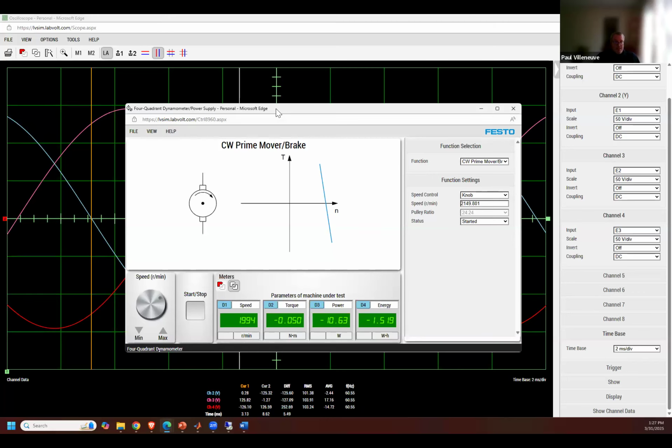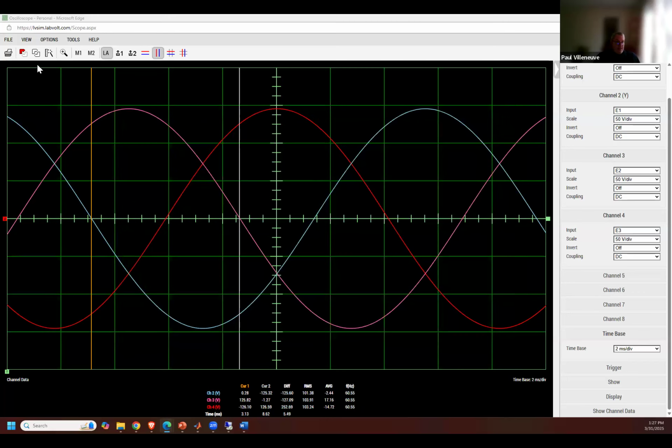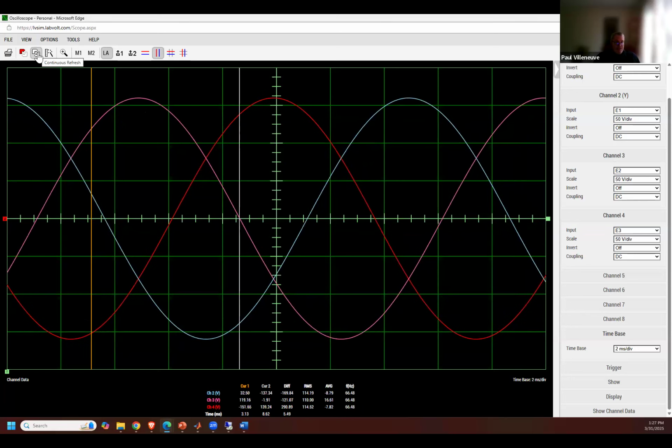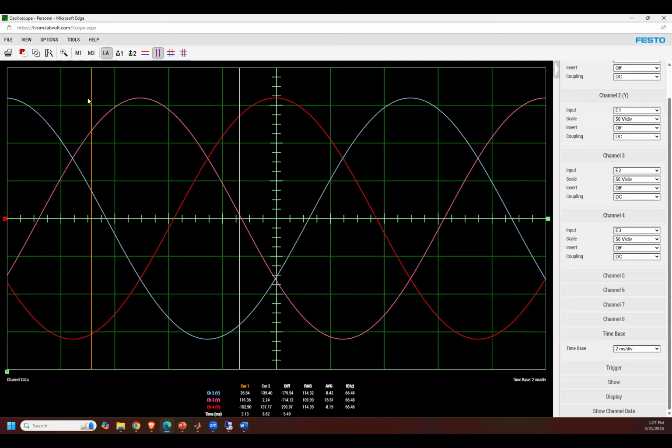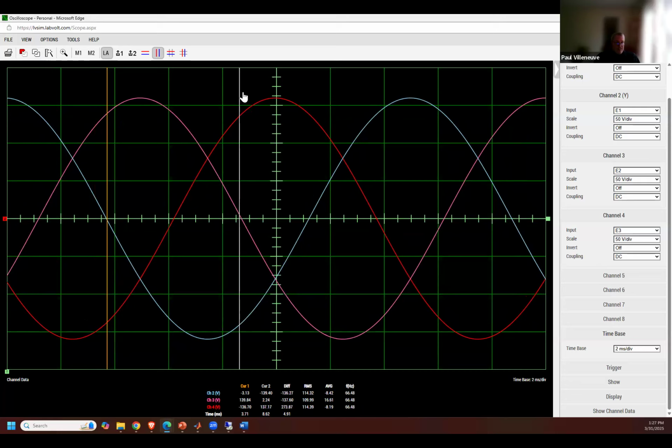1994, close enough, right? Now I'm going to make this so that I can get different data. And you can see it's much tighter, right? So I'm going to pause it here to here. And if I take the difference here, I can get it. But this one's a little bit harder because before when I said 1800 RPM, I was assuming 60 hertz. If the machine is running at 2000 RPM, the frequency is no longer going to be 60 hertz.